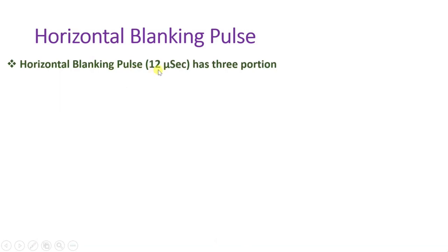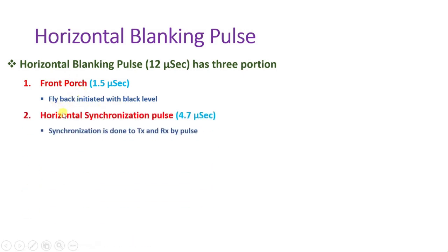Brighter than normal. H blanking and H retrace. The blanking time is slightly longer than the typical value of trace retrace time. As a result, a small portion of the trace is usually blanked at the start and end of each display line. This horizontal blanking effect is depicted by the black bars on the left and right of the image in Figure 7.6a. The black on the right edge corresponds to the front porch of the horizontal blanking, before the retrace begins. Generally, the horizontal retrace starts at the first edge, the leading edge, of the sync pulse.